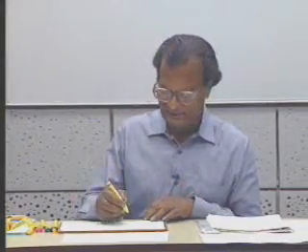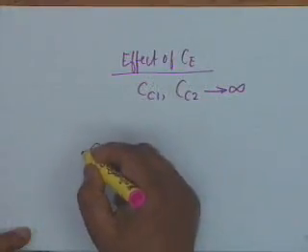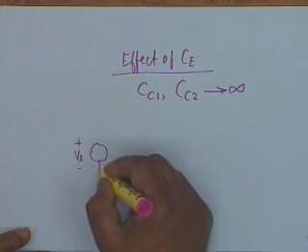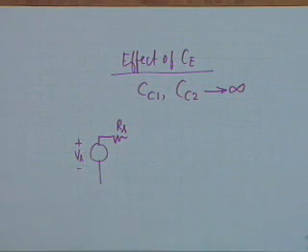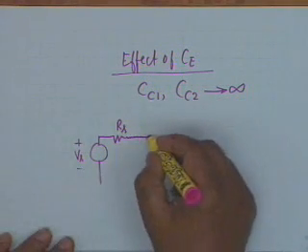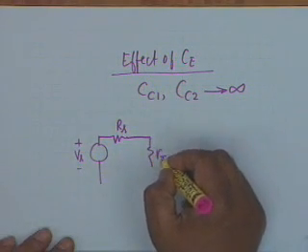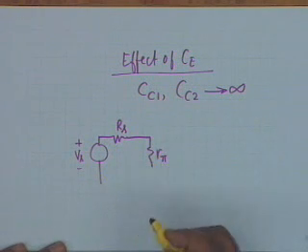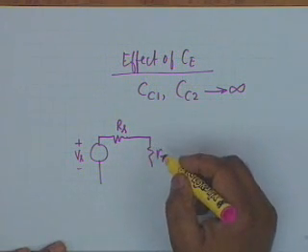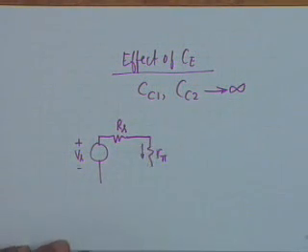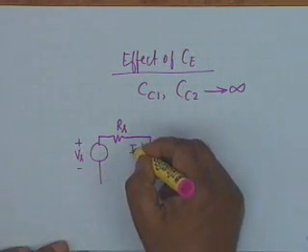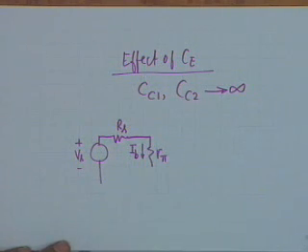Now if I do that, then my equivalent circuit becomes Vs, Rs, CC1 is taken as a short circuit and therefore I have R pi, and for a change let us use, instead of capital V, the base current. The RMS value shall be represented by I sub capital B. That is the reason why I am using the current here instead of the voltage.